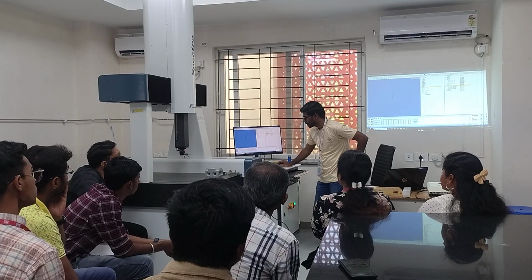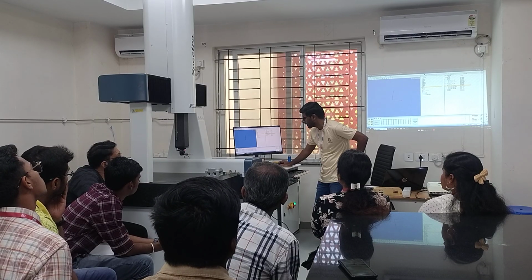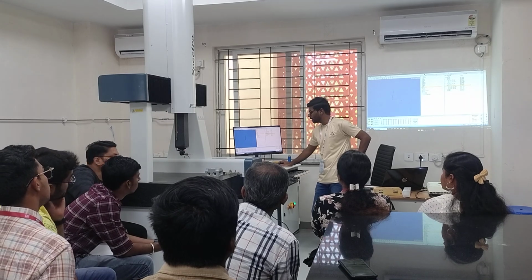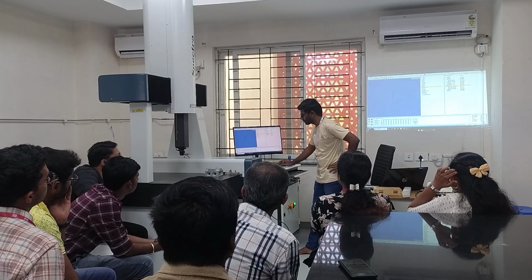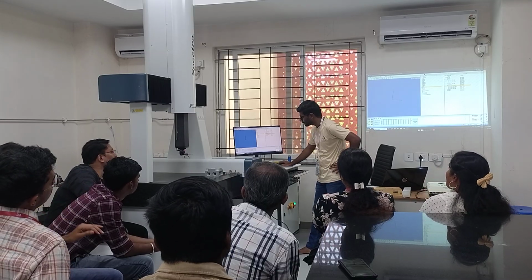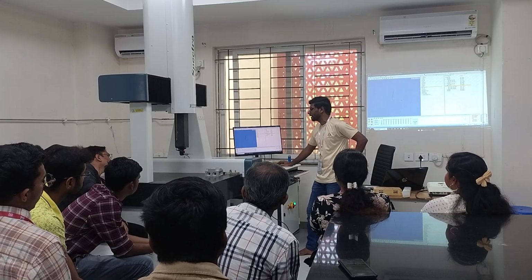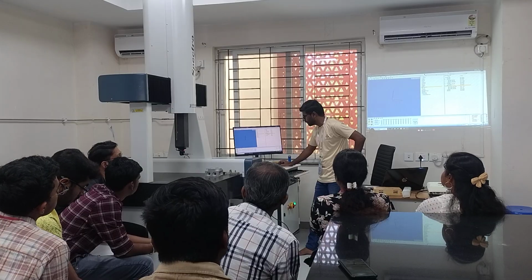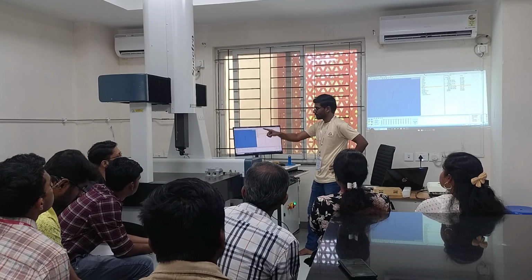So here are the options. Okay. A angle is there, B angle is there. We have different options. We can select either of the configurations. We can add different angles. Yes, we can add all the angles which are given. This is extensive actually. This is more than enough. I have added 1, 2, 3, 4 angles. Anyway, I am going to use only one, but I have added 4. Then we will keep on define and it will be defined. So our sensor is ready.